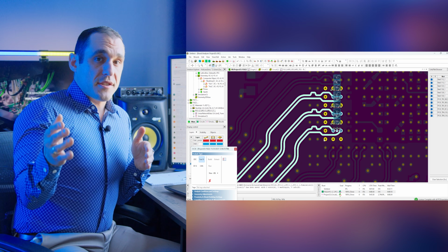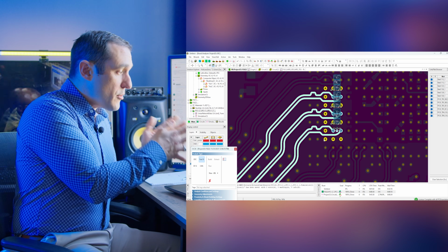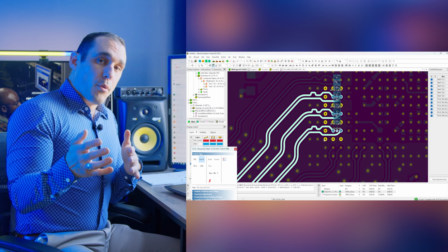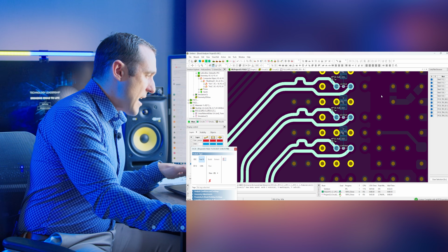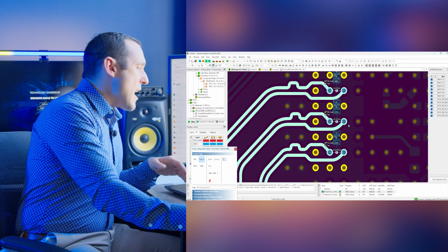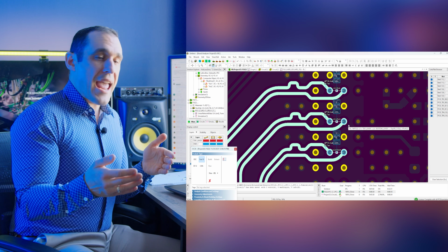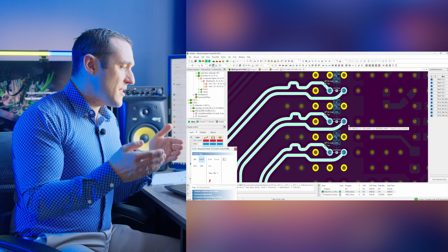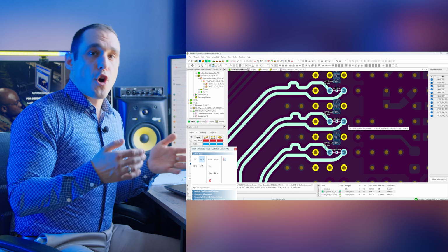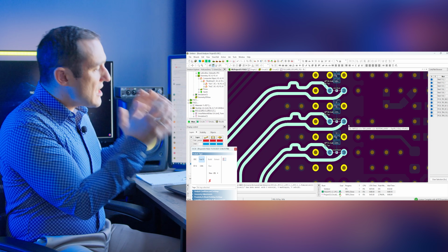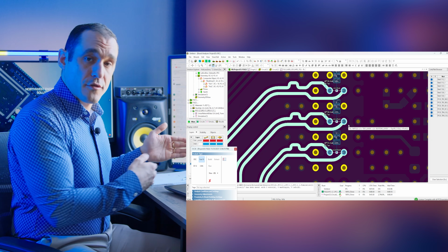Just like Polar Instruments, Simbeor also provides mixed mode S parameters, but it's doing it directly from your PCB layout. Now that's really important in a situation like we see here on screen, where we have these differential pairs coming out of a BGA region, and then we have to apply some length tuning. That length tuning can create mode conversion, and if there's too much mode conversion in this channel, the channel could be non-compliant with the interface standard. Mode conversion also creates jitter, and you'll be able to see the expected jitter in an eye diagram if you do an eye diagram simulation for these channels.